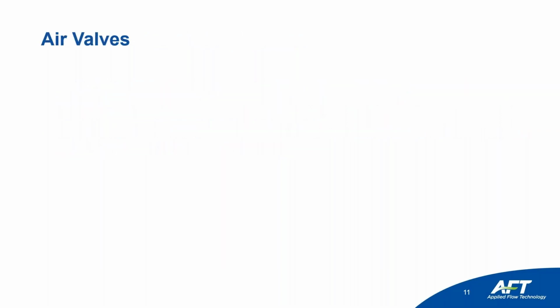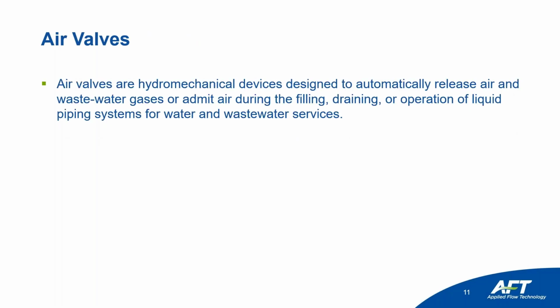So now that brings us to air valves. Air valves are hydromechanical devices designed to automatically release air in water and wastewater gases or emit air during filling, draining, and operation of the liquids piping system for water and wastewater services.